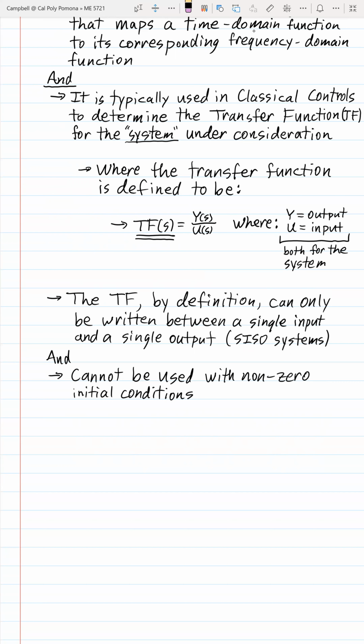And as you might remember, there are a couple different ways to get a dynamic system to do stuff. One is to have it have non-zero initial conditions. An example of that is if I have a pendulum, the idea of a pendulum having zero initial conditions would be that the pendulum is just hanging perfectly vertically. And of course, if it is, it's not going to move. If I have a non-zero initial condition, that's me pulling that pendulum off to some theta naught value for its initial angle. Then when I release that pendulum from that non-vertical position, the pendulum is going to start to oscillate.